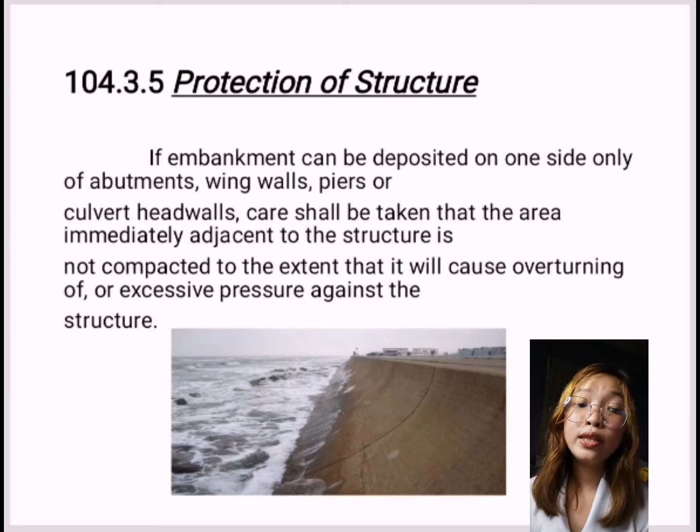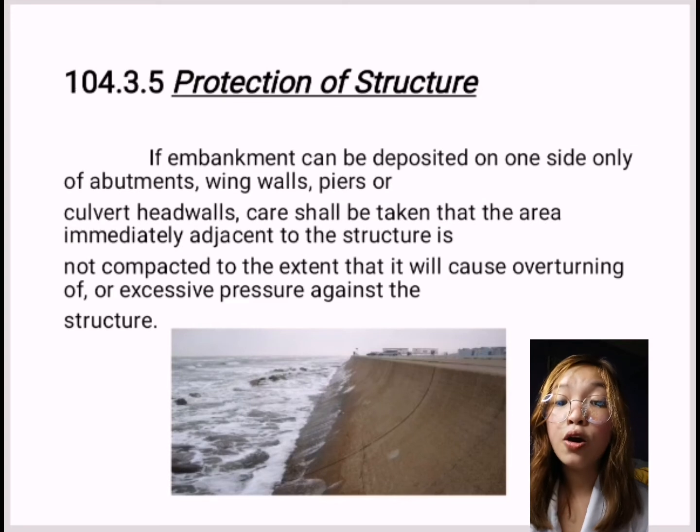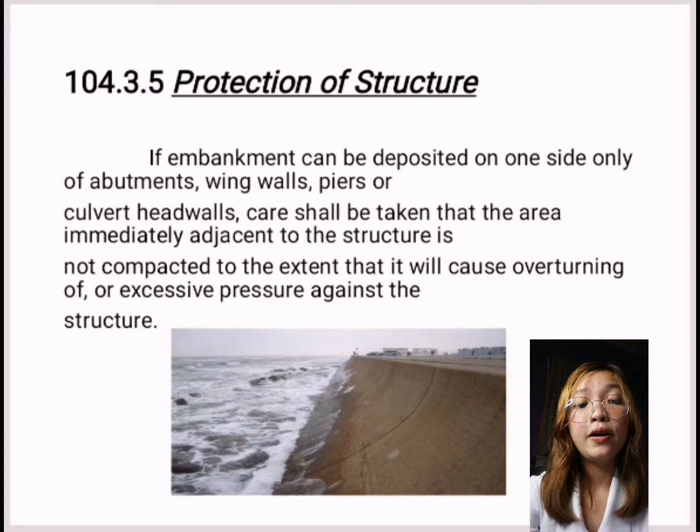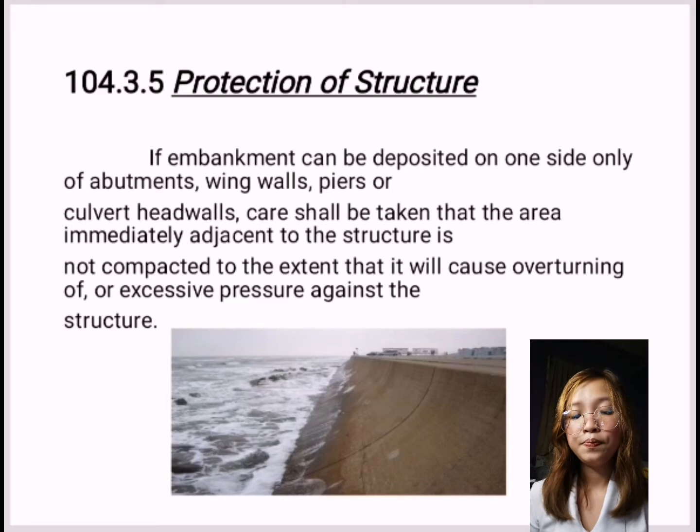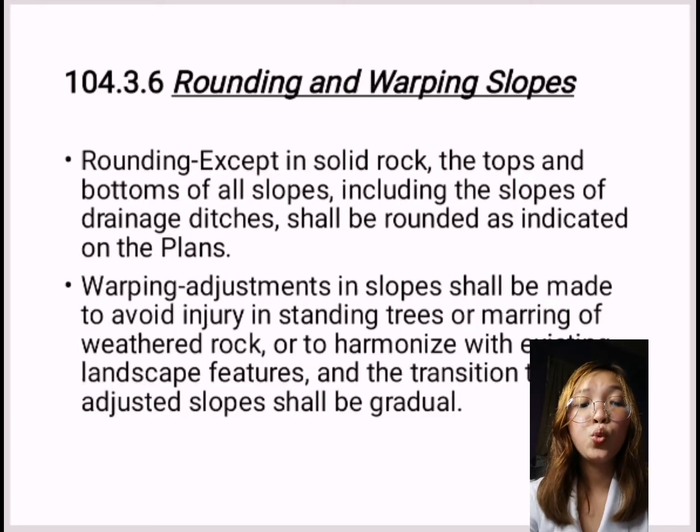So, we noted on the plans, the fill adjacent to the end bent of a bridge shall not be placed higher than the bottom of the backfill.